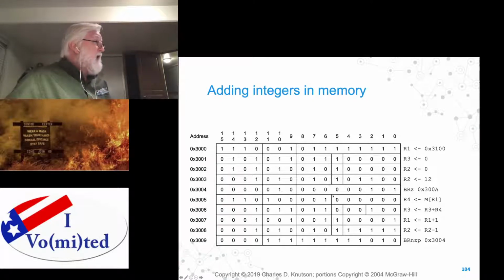All right. And if you look at this value, the incremented program counter is 3005 at this point, right? And this value is 5, right? 1, no 2s, and a 4. So 5, positive 5. So we take 3005 and we add 5 to it.